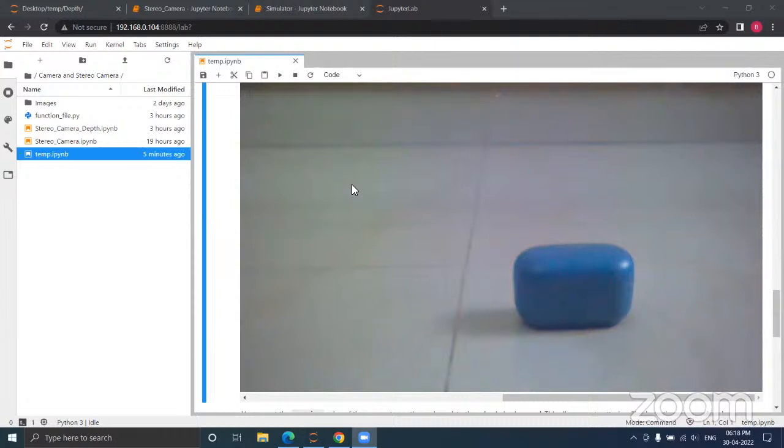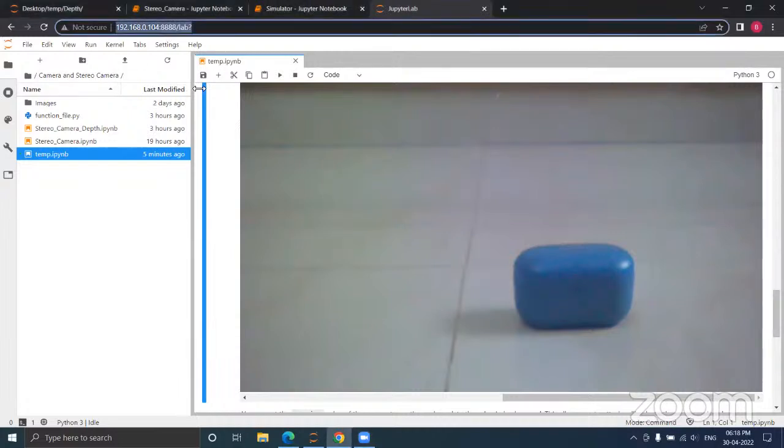Yes, I've connected to the Wi-Fi. By using the Wi-Fi module, I'm able to interface and get your output. That's how you can see I'm using the Jupyter notebook via Wi-Fi. To link your Jetson board, you don't need to use only Wi-Fi. You could use a wired connection also, maybe a USB cable. I was showing you a micro USB, right? You can use that to connect, interface and program.